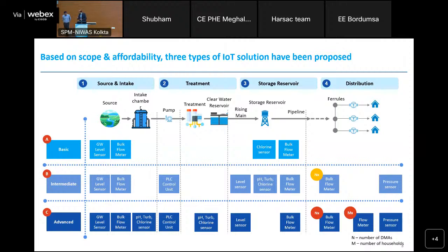And one more question was about the PLC controller, what is the cost generally range? No, here we are not using a PLC, only a pump controller. We are using an L&T contactor and connecting the float switches. So it all works completely as an independent system with wireless communication.